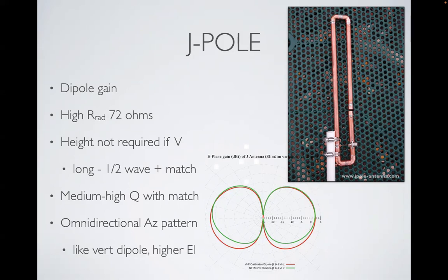And the looping back part at the top, that's just sort of a folded dipole, slightly changing the impedance and thus changing the calculations. But again, it's a lot like an end-fed half-wave. And you have this matching section. But the interesting thing about it is that it's out in the open. And so the fields interact between the half-wave dipole part and the transmission line transformer. So they influence one another, and that helps favorably push the pattern up even more. So it's an interesting antenna.